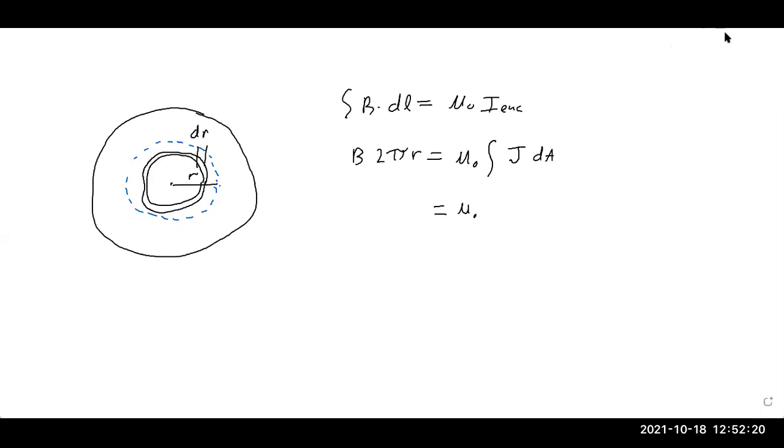So 2 pi r dr. So 2 pi r is our circumference. We're going to give it a dr thickness. Good. And the current density at that distance was 3 r amps per meter cubed. This weird unit, when multiplied by r with that hidden meters in it, gives a current density of amps per meter squared, as it normally should.